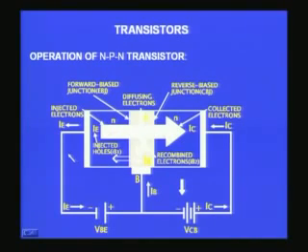There is no current gain, the current actually is falling. IE is slightly less than IC because some IB is lost, but still because almost the same IE is flowing through the base emitter junction and the collector base junction, the voltage developed in the collector region will be larger, and therefore there is an amplification associated with this. So this is the basic action of a transistor.